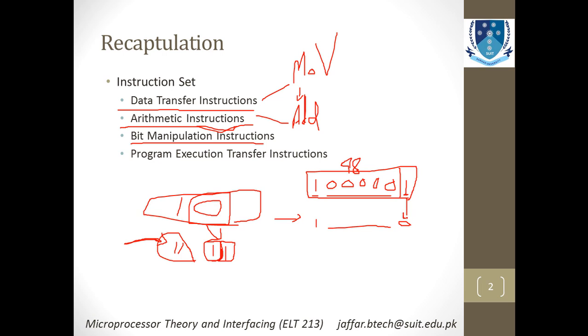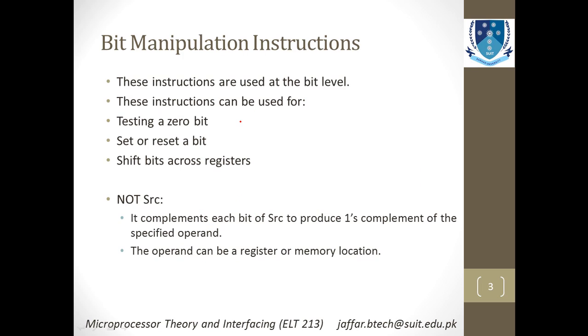This is known as bit manipulation, in which you can manipulate or toggle one or more bits as specified by your desired functions and outcomes. If you want to toggle these 2 bits, you can use bit manipulation instructions to toggle them. It will become 1 0, and you do not have to reprocess or transmit all the data. This saves energy and processing time as well. This will be very useful in your coming life, inshallah. Let's start with the details of the bit manipulation instructions.